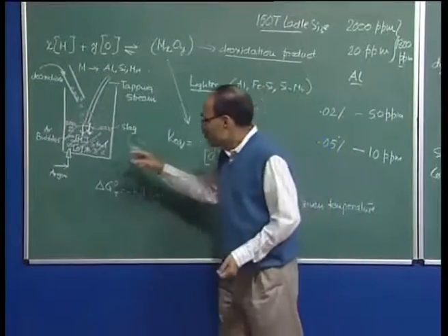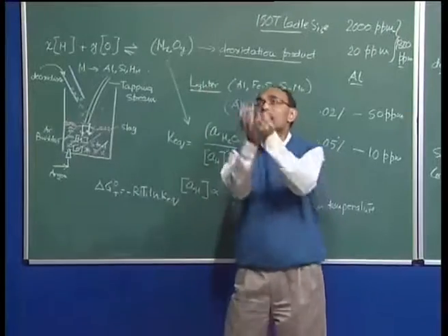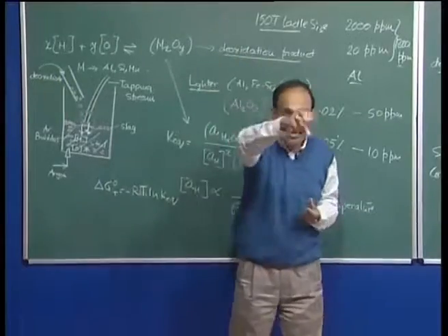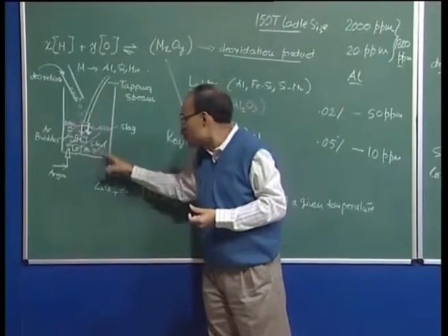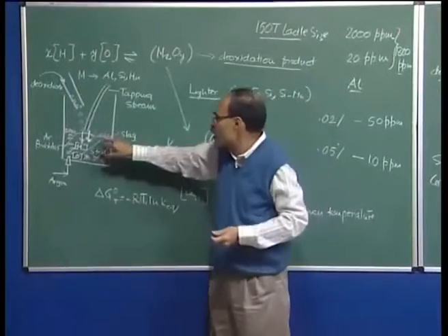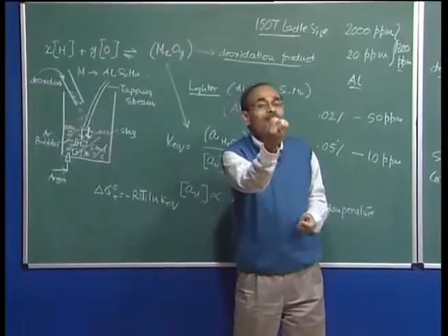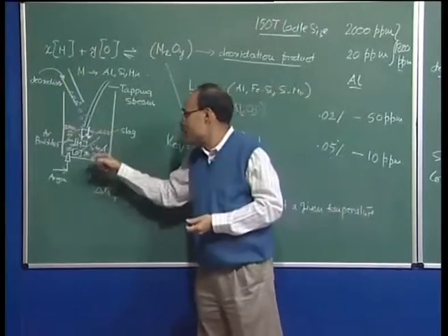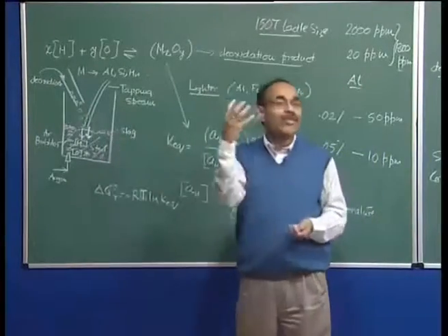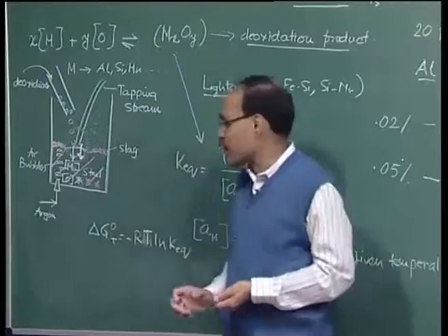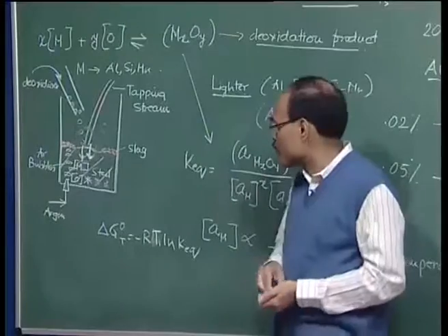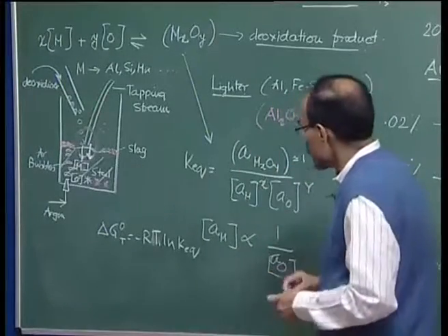Okay? And typically, the deoxidation products rise to the slag metal interface, and the slag captures the inclusion. The slag removes these non-metallic or harmful inclusions, but the inclusions really stay for some amount of time in the vicinity of the slag before they are completely captured by the slag itself, and this is referred to in steel making reactors as the dwell time of the inclusions, or the dwell time of the deoxidation products. Okay, they have to dwell in the vicinity of the slag for some amount of time before being completely captured by the slag layer itself.